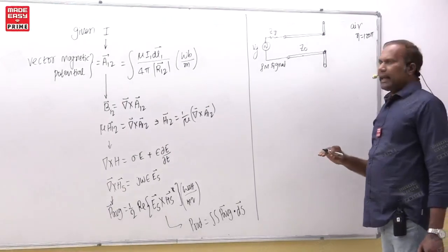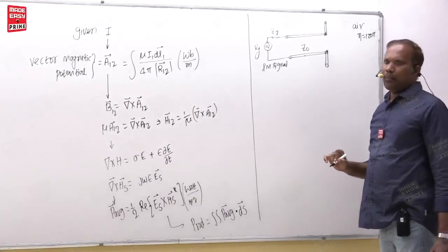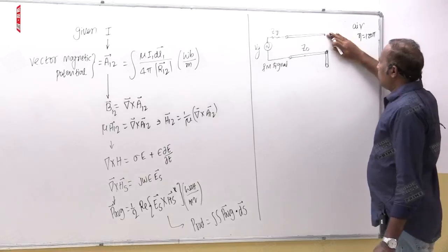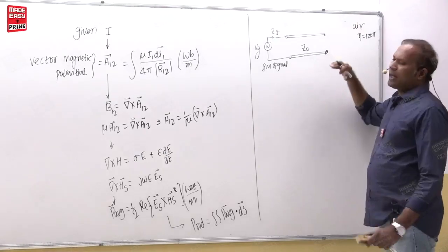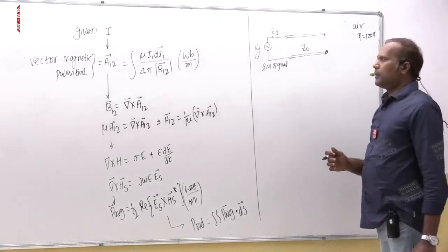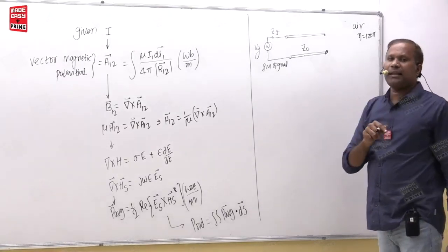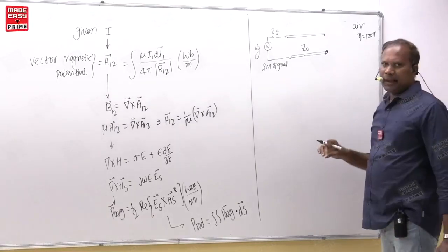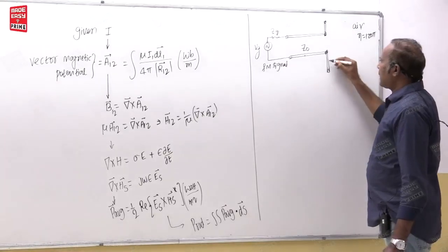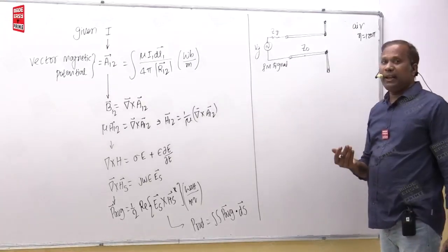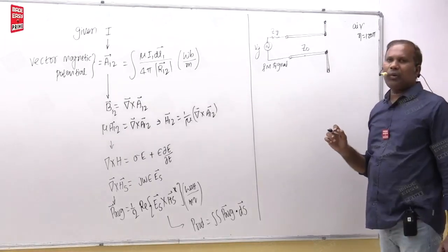That is one thing. The second thing is efficient radiation of the EM energy. For example, if you ask these open end transmission lines to radiate, they just radiate. In which direction we do not know, but the thing is, in the desired direction they cannot radiate the EM energy. So if we have an antenna, if the antenna has gain, antenna has directivity, it means in a particular direction we can radiate without wasting the energy.